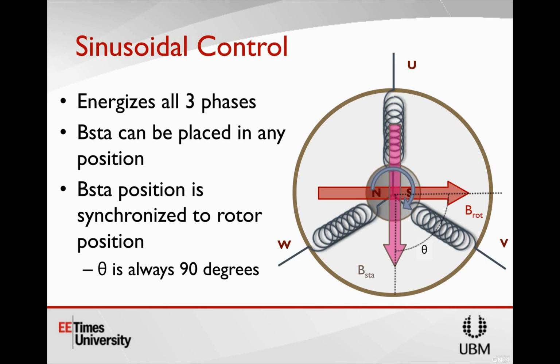One of the advanced techniques available in the market is called high-frequency injection or initial position detection. It injects high-frequency sinusoids into the phases of the stator, looks at the feedback currents based on that injection, and figures out the relative angle of the rotor. This is a very advanced technique that can be tricky to tune and adjust, but it can allow you to start very quickly and not suffer as many of the penalties of the sensorless startup that we talked about.